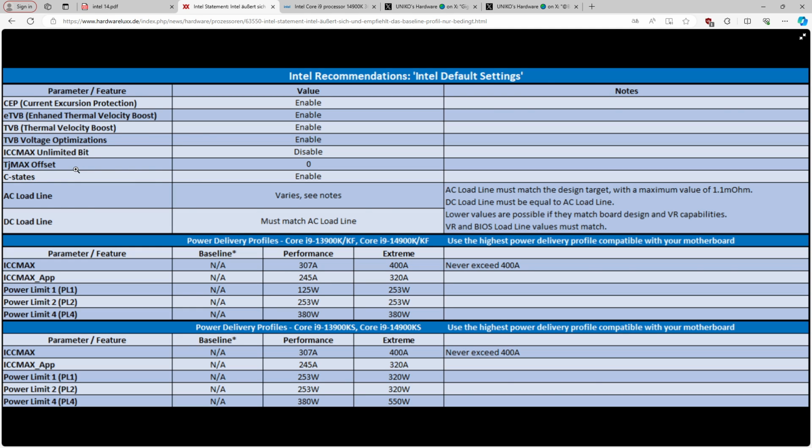So I personally would think, I'm not sure how stable it's going to be, but from a longevity perspective, it is better to have a CPU averaging 1.45 volts with some high transient spikes, because the biggest transient spikes you're going to get are going to be at high load, not low load. So the fact that at low load you're at 1.45 volts, that's not really a big deal. You're not going to have a 200 millivolt overshoot when pulling 60 amps, right?